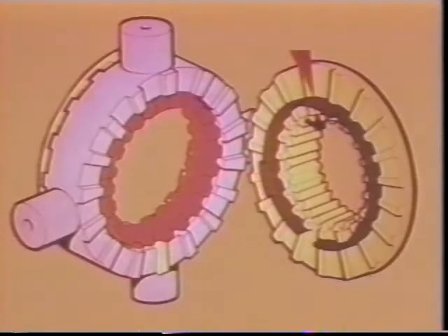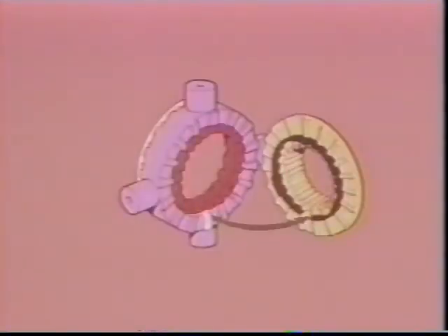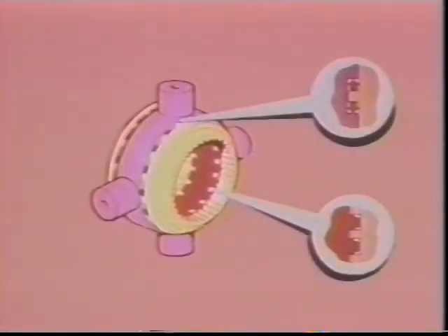With the driven clutch member removed, you can see that the rotatable holdout ring is held in position around the inner row of fixed clutch teeth. The gap in the holdout ring meshes with the bottom portion of the long tooth or key of the cross. The teeth on the holdout ring sit in the wide slots of the center cam. The inner row of clutch teeth on the driven clutch members fit between the teeth of the center cam, while the outer row of clutch teeth sits loose in the large gap between the teeth of the cross.